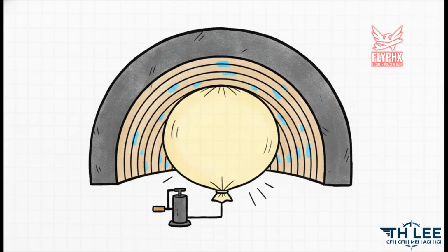Now, monocoque design is incredibly weight efficient because it completely eliminates all that heavy internal bracing, but early on it was notoriously complex to build. Case in point, here's a fantastic historical anecdote from 1918. Aviation pioneer Jack Northrop devised a totally new way to construct a monocoque fuselage for the Lockheed S-1 Racer. Instead of painstakingly gluing hundreds of tiny strips of wood, he took 3 large sets of spruce strips, soaked them in glue, and laid them inside a semicircular concrete mold.